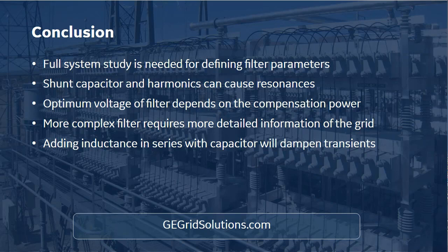Okay, then there's a question: is there a rule of thumb for kVAr / kV when evaluating the practicality? I would say that the best option, or at least the cheapest, economically best option, is always to use as high a kVAr rating for the unit as possible. But then again, the voltage also depends a little bit on the bank connection.